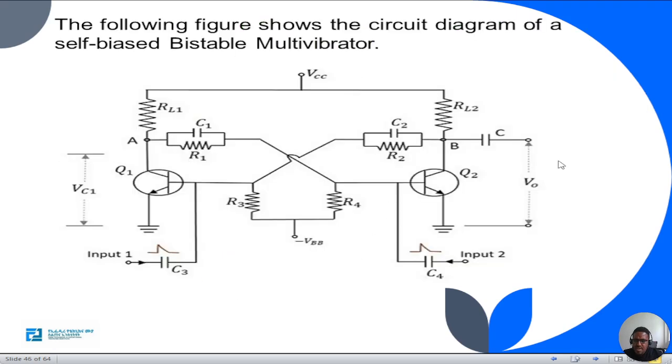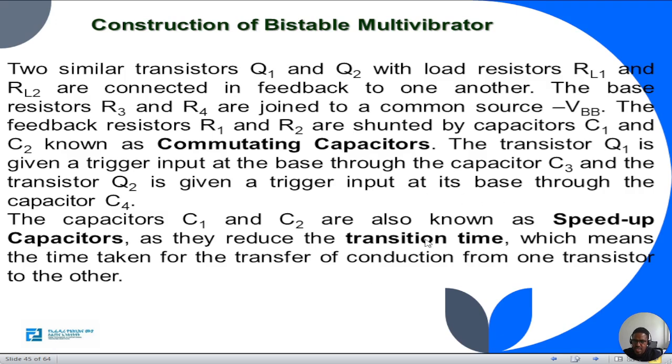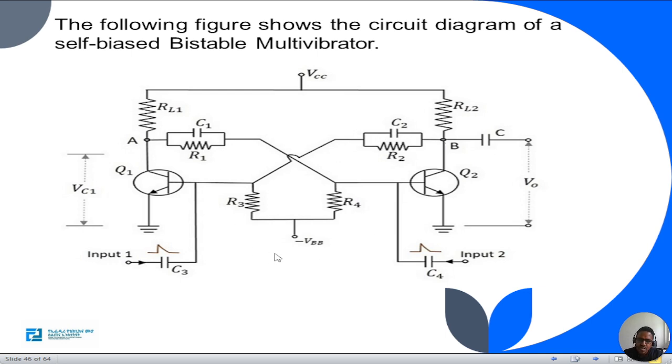So it looks like this, the bistable multivibrator. C1 with R1 in parallel, that is what I said for speed up capacitor purpose, thus capacitor 1, capacitor 2. From this collector to the base of Q1, from this collector to the base of Q2. So both of them are in the output we can get by triggering. If you need high, trigger 1. If you need low, trigger 2. That becomes stable. Both sides are stable output.